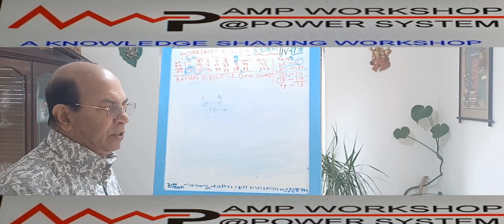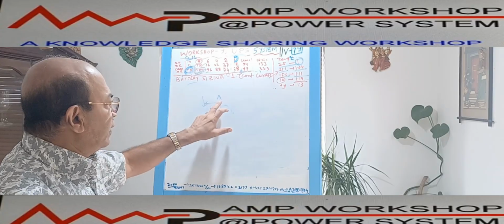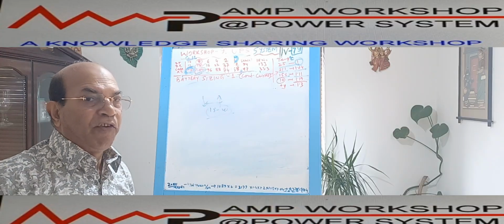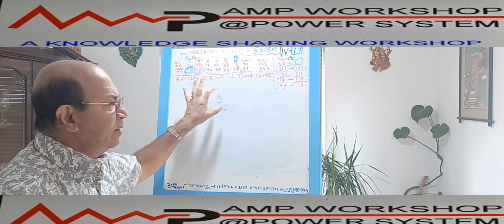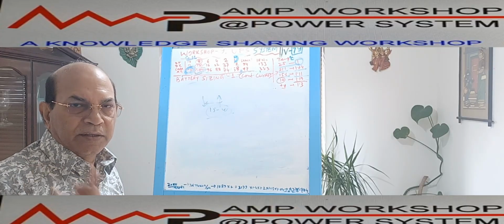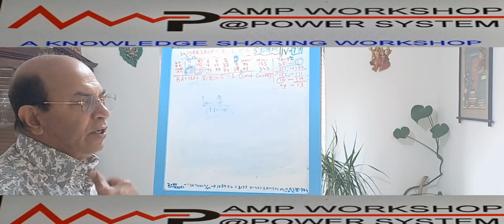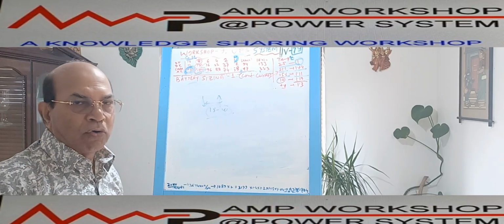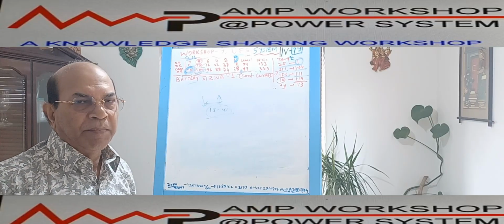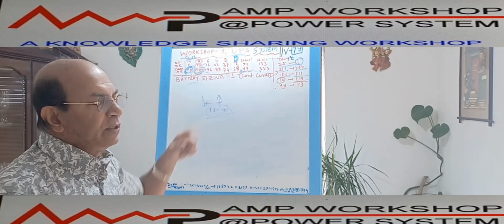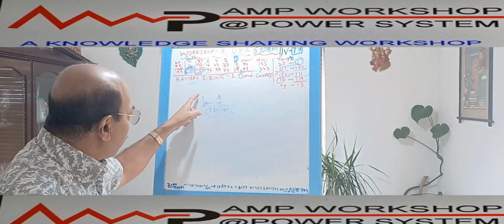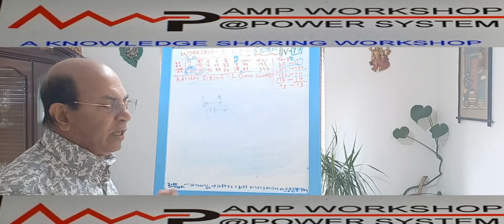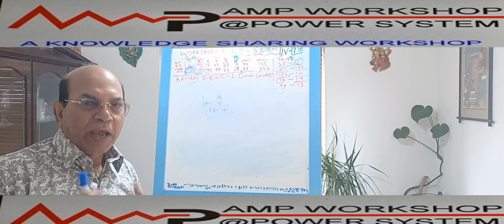That is one application. Second, it may happen that the normal power supply fails and immediately the emergency diesel generator fails to start. It is a mechanical device. This emergency diesel generator has a diesel engine, which is the driver. It runs the alternator, and the alternator produces current. But that diesel engine may fail to start, because there are so many controls. If it fails to start, then what will happen? Till the problem of the diesel generator is troubleshot, or the normal power which dropped gets started, I have to back up my critical load by the UPS. So it may go 2 hours, 8 hours, 4 hours. We don't know.